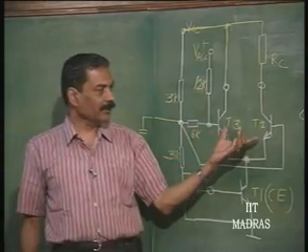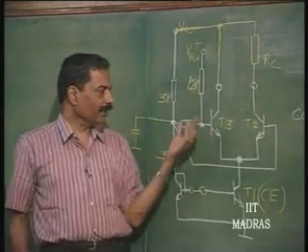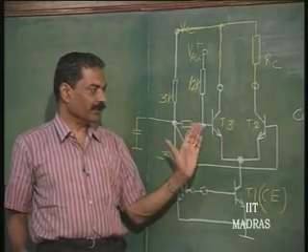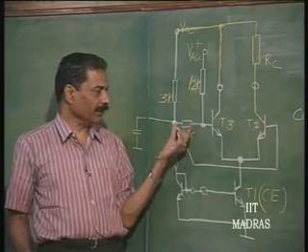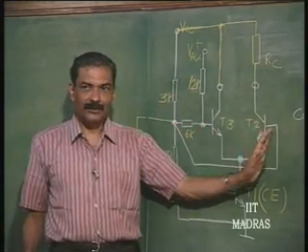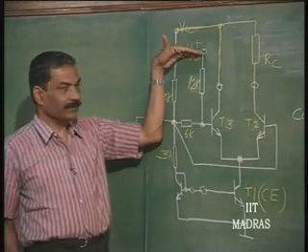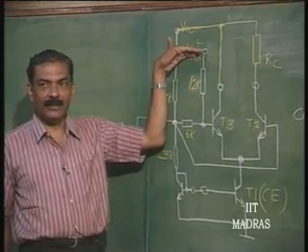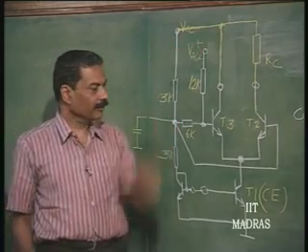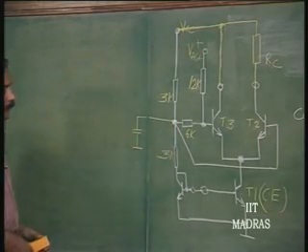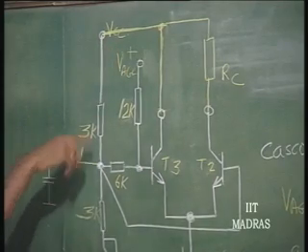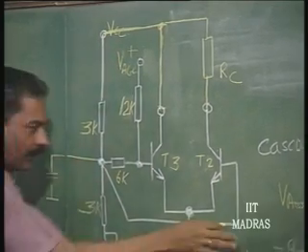We had earlier learnt about the differential amplifier, and we have seen that as we apply a positive voltage here, the current gets shifted to this. As we apply a negative voltage, the current gets shifted to this. So, by applying a suitable voltage, which we are calling VAGC, we will understand why this is called AGC later. By varying this VAGC voltage applied at this point, we can therefore control the gain.